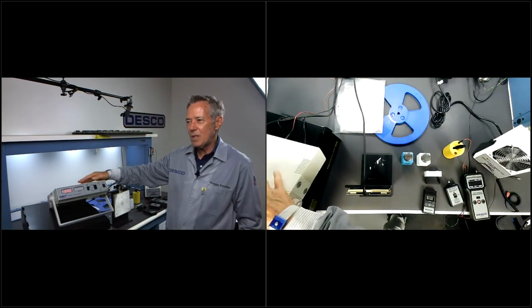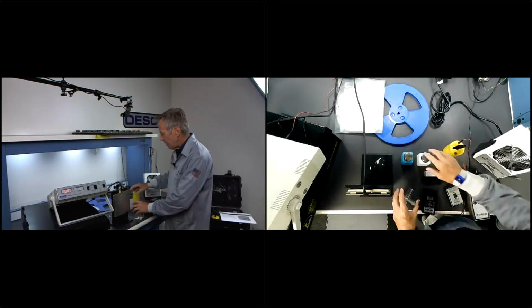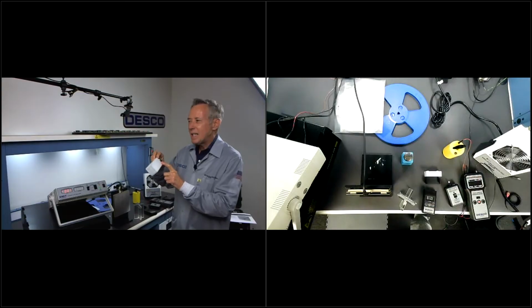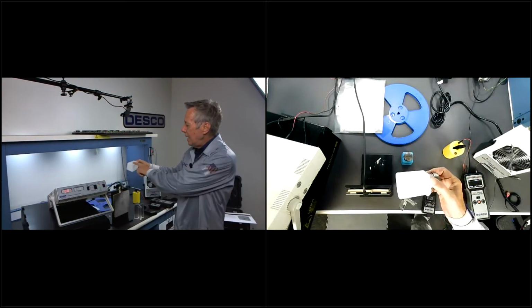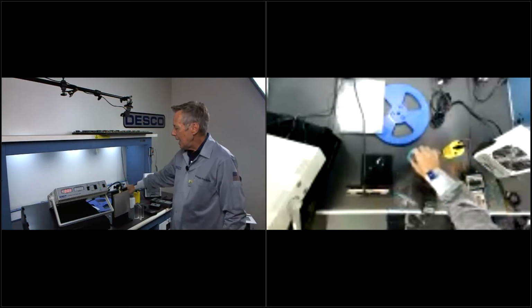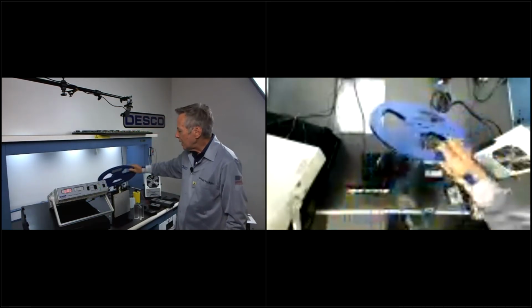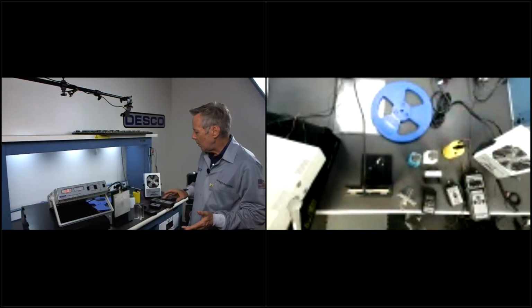And then I have what we call a charge plate analyzer. This is probably the most sophisticated piece of equipment you would have in your static control program. You would purchase this equipment primarily to calibrate ionizers, but you can use it to measure charges, all kinds of things in your static control program. I have some other examples. I have a regular non-ESD Menda bottle here, a chemical dispenser. I have an ESD version. I have some ESD bags back here. I have a regular reel from a tape and reel. So I'll give you an example of some typical things that we would use.